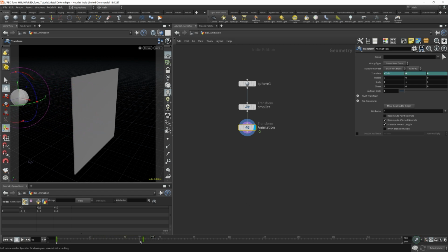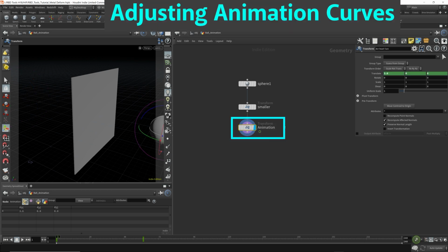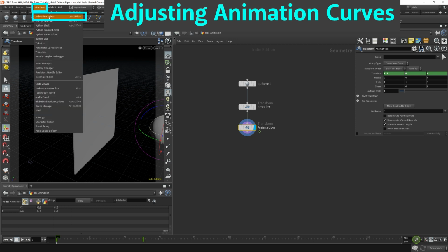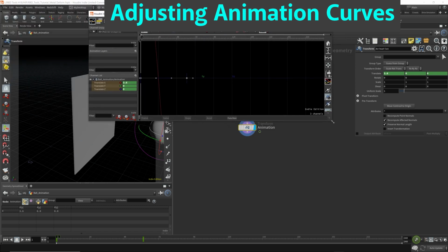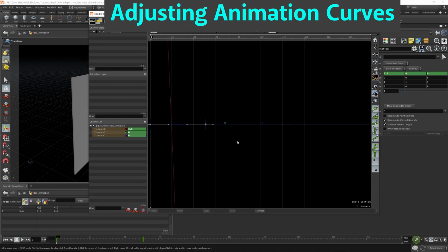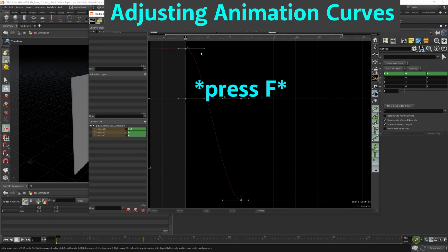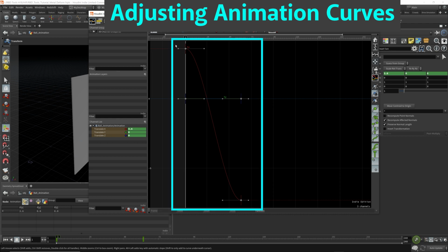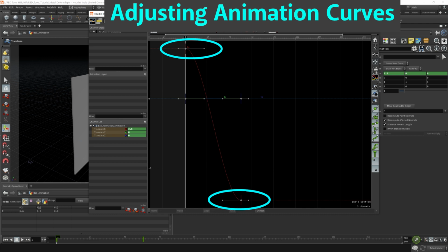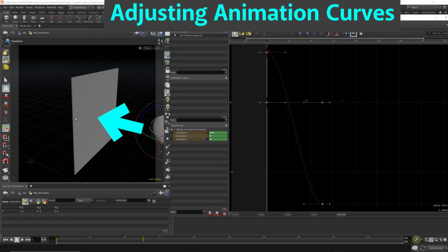That's pretty cool. We can actually do a little more to the animation to have it more smooth. Select this node that contains the keyframes. Come here to Windows, Animation Editor. Make this a little bigger. Now with the mouse here, press F, and it will focus the screen on the keyframes that you have created. So there's 2 Bezier curves. I want this to appear to whoosh and slow down. Actually, I want it to slowly come in, then speed up, something like that.